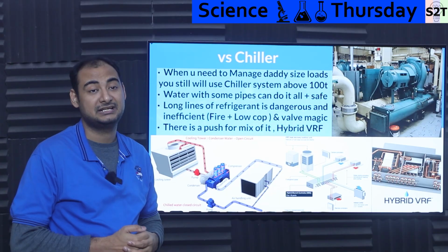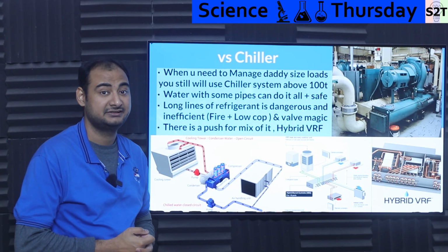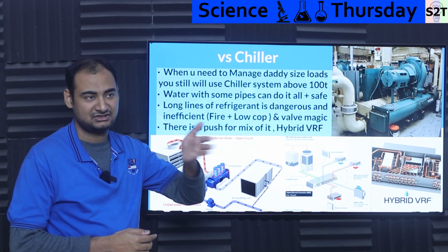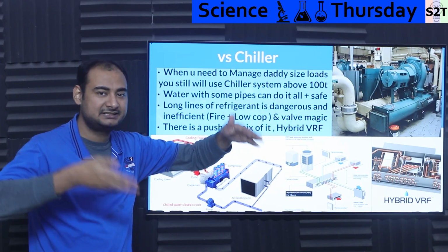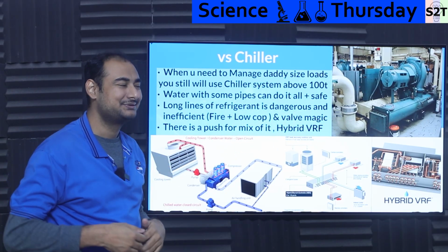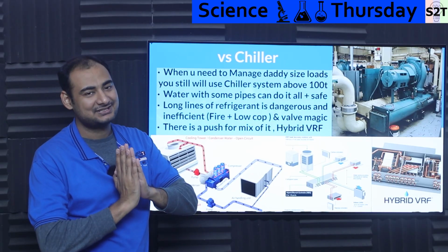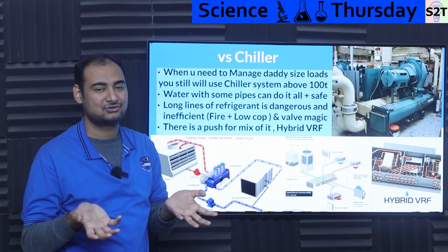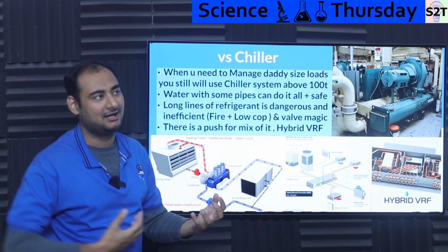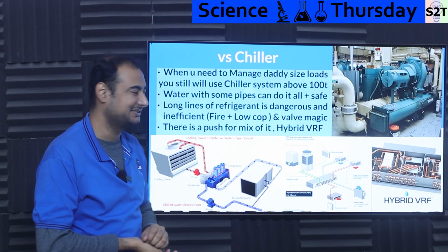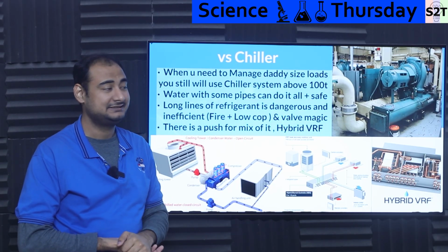First, they can transport energy much further than refrigerant can. Refrigerant, there is a very serious chance if you have very long refrigerant line, it might self go do the phase change. So that's an issue. Another aspect is your compressor will start to stall out. So compressor has upper limit. Water pumps, yeah, bro, it does not care.